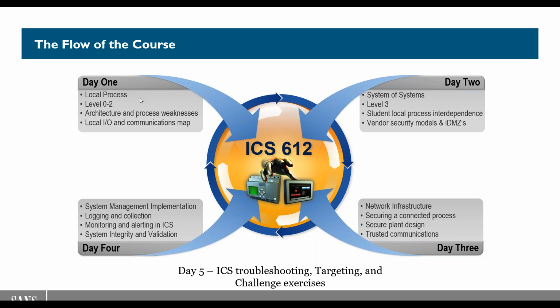of course, but basically the students will come in on day 5 and the instructor team will have modified the environment in the evening of day 4. And the students will have to troubleshoot the list of complaints from the operators or from peers or process alarms to identify where a misconfiguration is, where a fault is, where a device may have failed, where there may be some rule sets in error. So not necessarily direct step-by-step lab driven, but outcome driven, more what they would experience when they return to work.